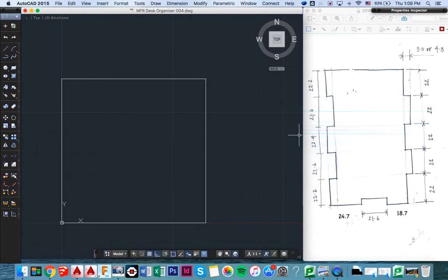Now, you can see over here on our drawing that these are the spacings between the tabs, and like I said, these spacings are really important. You'll notice on this side they're 22, but on this side they're slightly different. I'll explain that to you. Over here this is 22, but we want it to tightly interlock with this tab here, so we've made this tab 0.2 smaller. So 22, taking 0.2 off that side, 0.2 off that side, take away 0.4, is 21.6. So when we go through this, you'll need to make sure you get that exactly right. This is a little bit later.